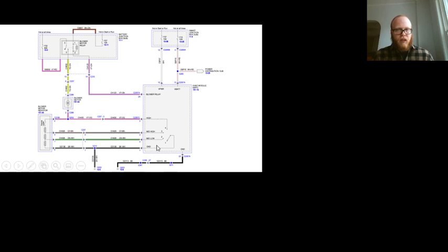Let's do the medium low now, I guess. Why not? In this case, we come through our relay, through the motor, go through one resistor to come to medium low, and then we'll be able to flow through to ground. And then at the lowest speed, go through 1, 2, 3, and I just go through ground. You see how the switch is just not doing anything.